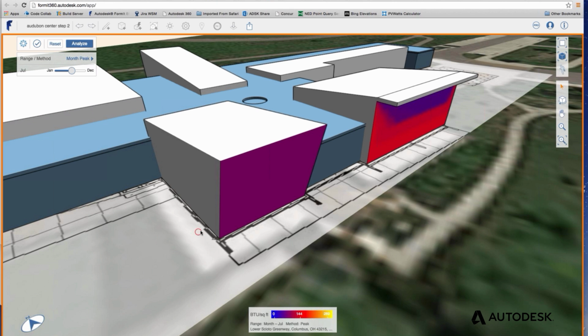Okay, so that's interesting. The one surface that has the slanted surface now only shows me 47 BTU per square foot. Just by doing this little move, I can cut down the amount of energy received in the summer by half. The overhang was maybe not quite as efficient. Obviously it depends on the direction of the light here. So some part of it is nicely shaded.